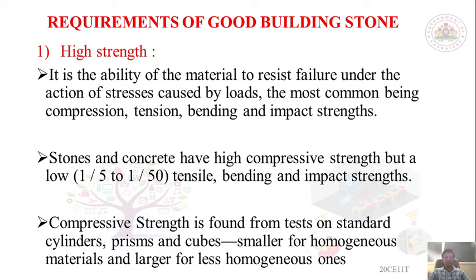High strength is the ability of any material to resist failure under the action of stresses. It is the ability of the stone to resist failure under the action of stresses caused by the loads, the most common being compression, tension, bending and impact. Stones and concrete have a very high compressive strength, but tensile, bending and impact strengths that are very low, about 1/5 to 1/50th of it. So stone is good at compression.